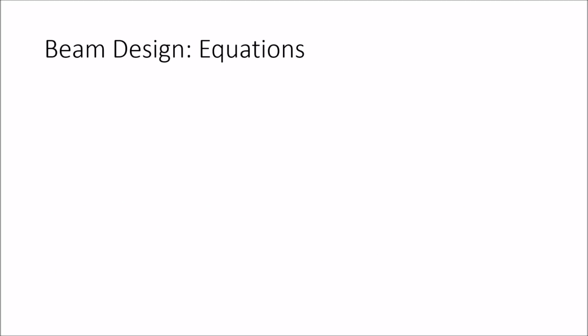Usually in class we will be dealing with rectangles and I-beams for beam design. Because of that, we can use some equations to help us design the factors. Remember, for I-beams we will mostly be using information provided in manufacturer charts, whereas rectangular cross-sections are common enough that they can be used with wood or any other material.